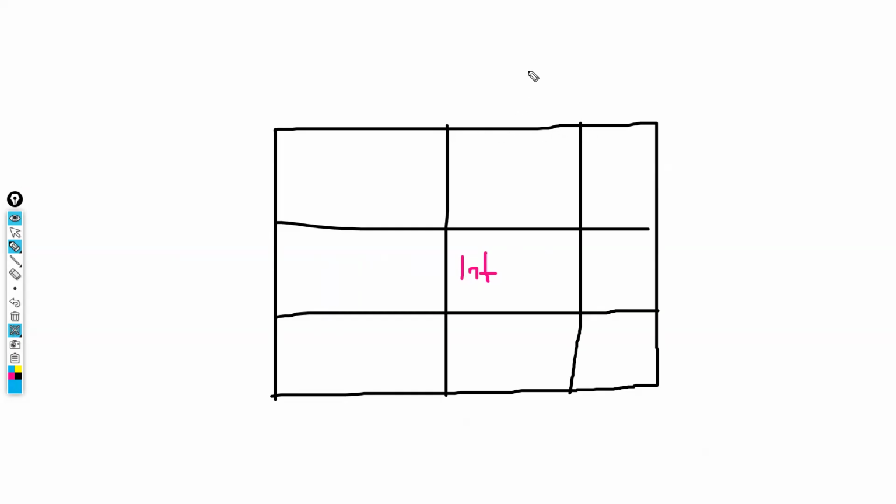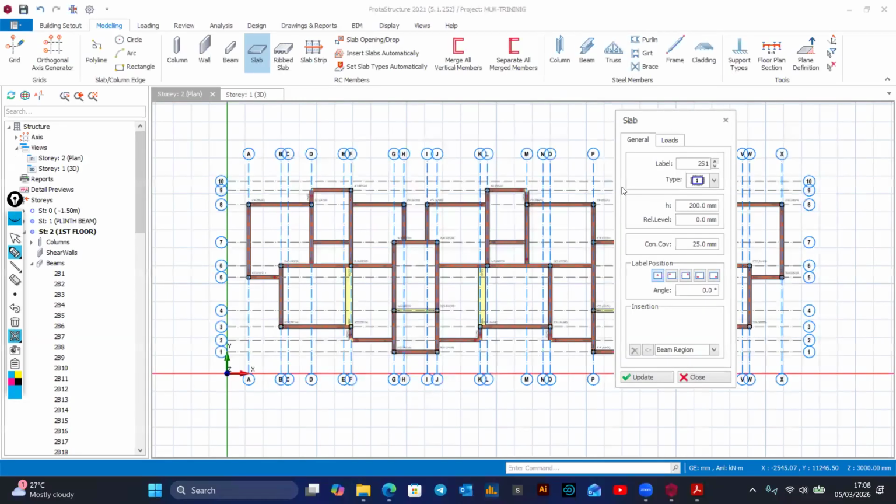It's not continuing on this other side. This is going to be one short edge discontinuous. Okay? But then this one, two edges discontinuous. You don't have to cram this. Okay? The software has it here. You just need to know the arrangement of your floor.